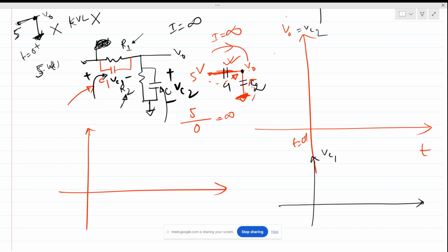We are talking about the capacitive impedance being very small, but there is capacitive impedance, and that is decided by these capacitors only. R1 and R2 play nothing at t equals 0 plus in this circuit, because they come in parallel, and this impedance is very much less than this R2. So only the two capacitors are present. Okay, now got it, Amit.